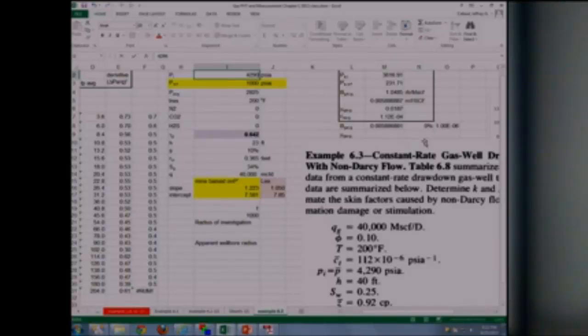One of the reasons they ran an arithmetic average of the flowing pressure and the average pressure is they were producing a constant bottom hole flowing pressure. But here, we're producing a constant rate, and our bottom hole flowing pressure is constantly changing. So, those are some small innuendos.